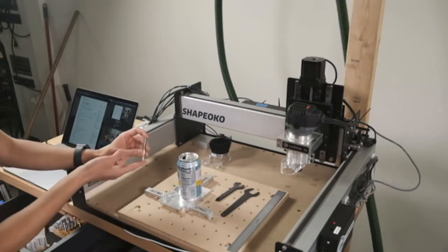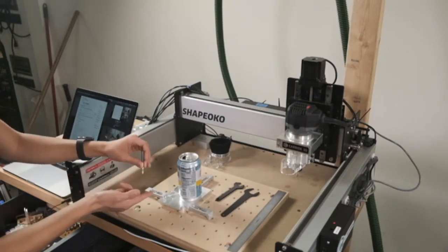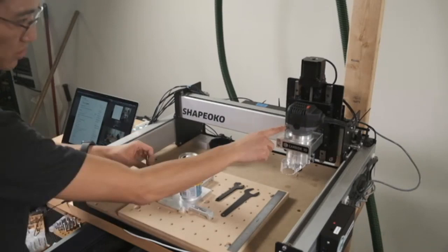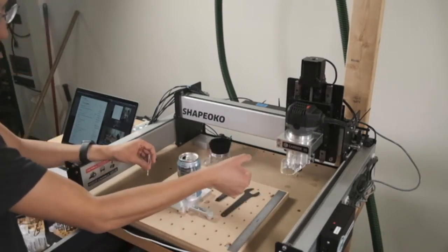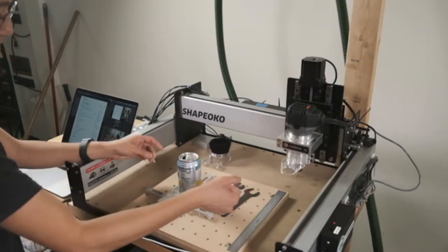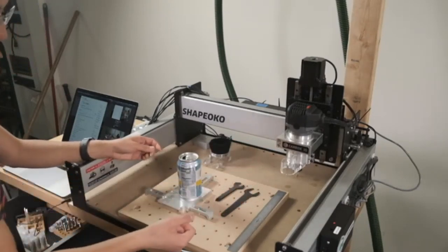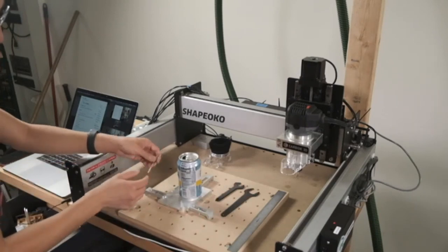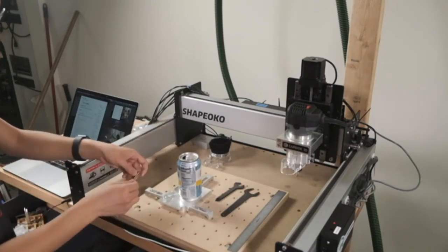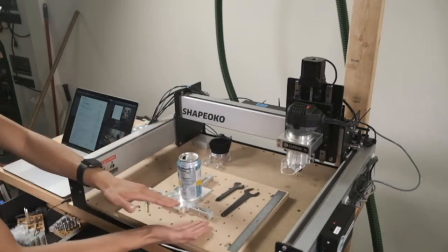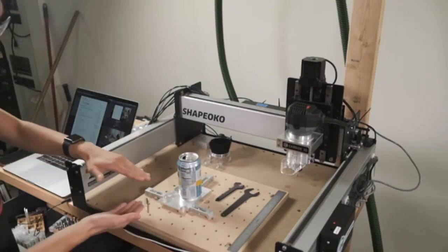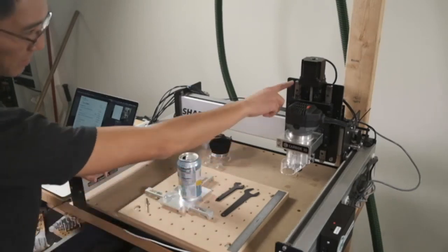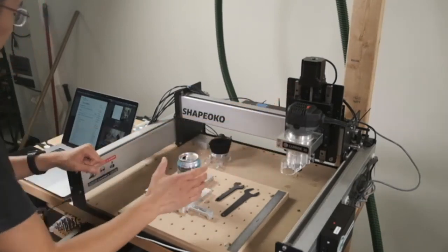And the length of the tool that you can utilize is restricted by how much travel you have. Because if you had a 6-inch end mill, but it can only change its height by 3.5 inches, then you can't use that full 6 inches of that tool. So in theory, you can machine anything that'll fit here, but you can only machine a slice of it, a layer of it, that is the length of your travel.